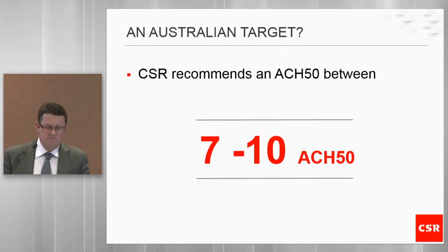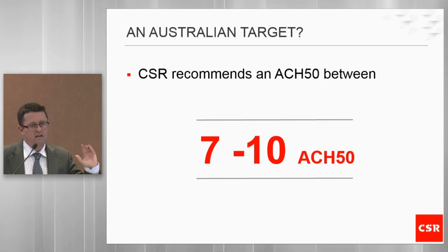So I guess on this basis, we're going to propose a figure here, and that figure is going to be on the basis that if we do what the building code requires us to do, we seal the internal layer of the external wall. We pay attention to things like the joints at the skirtings and architraves and the ceiling junction. We just look at good quality construction, seal construction gaps, put dampeners in our ventilation system.